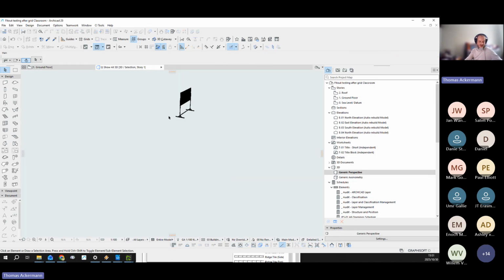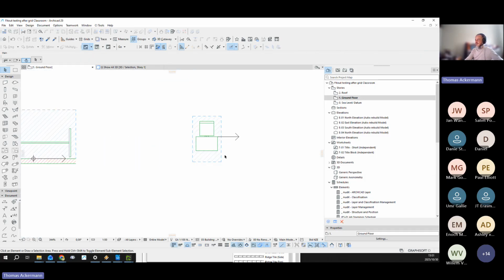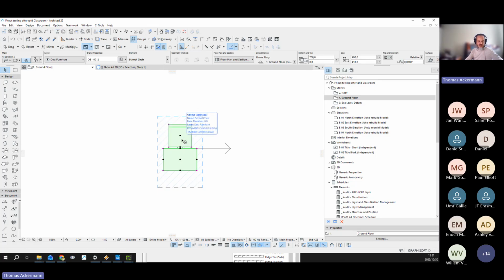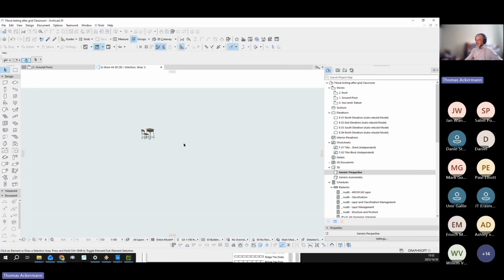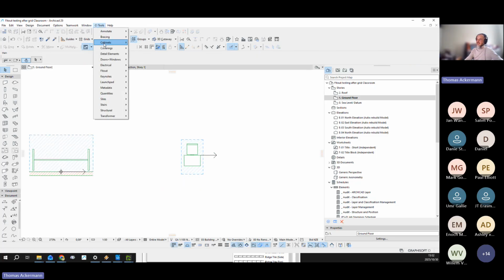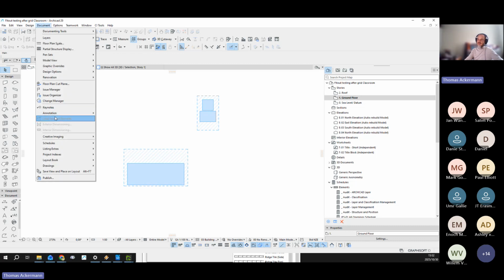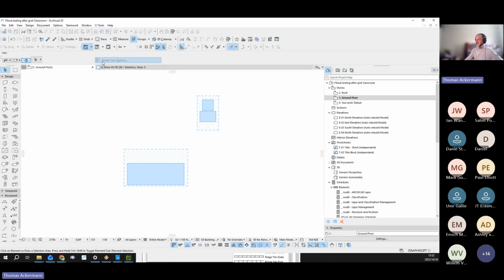And I'm just going to show you. So we've got a nice blackboard over here that we're going to use for this classroom. And at the same time, we've got a desk and a chair that I've placed in a freestanding clearance space that we're now going to use. Now, what you do is you basically select that, you go to the CI Tools fit out, you save it as a set. And once you've got the sets, you place the sets. I'm going to model the options here.